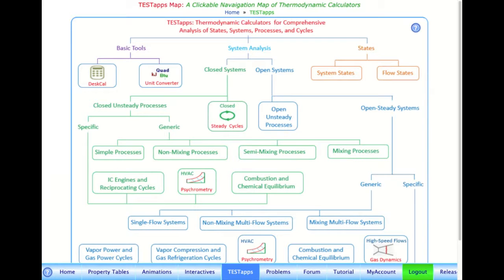In the problem at hand, we have a steady flow through a turbine. The fluid is steam. In the process, one of the process is that it is steady state, no time dependency, it's not building up over time. Also, as stated in the problem, it's an adiabatic process. And adiabatic means that there's no heat transfer. And so with that in mind, we will then be able to solve the problem at hand.